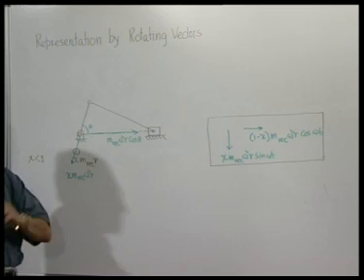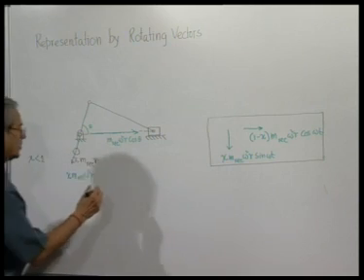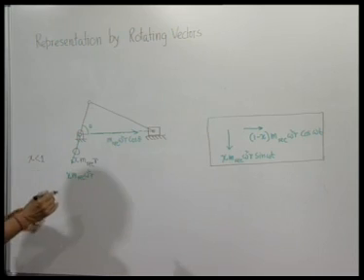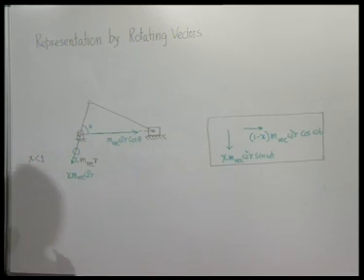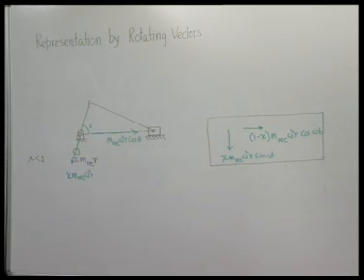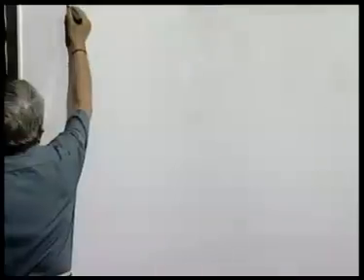neutralized the primary force. To neutralize the secondary force, we have to create physically another crank, which will be the secondary crank, and add another mass, but then the system becomes very complicated. However, in very special situations where it is absolutely essential to neutralize as much force as possible, we adopt such techniques. This technique is often called the Lanchester balancing technique.